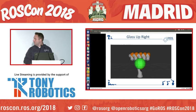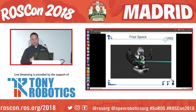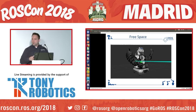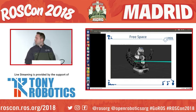I think I have one more. And then here's a complex free space motion planning problem with a high degree of freedom, where it's given a joint interpolated trajectory, and it's able to use the convex collision checking to push itself out around the table and come up with a collision-free trajectory.